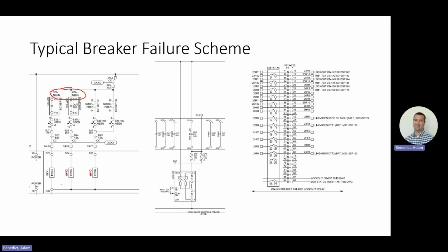And usually you'll see just one input. This one, they do separate inputs. I think part of it is so that if there's not enough fault current in one of the nodes, they can do a no current BFI. And they have more flexibility on the settings that way.